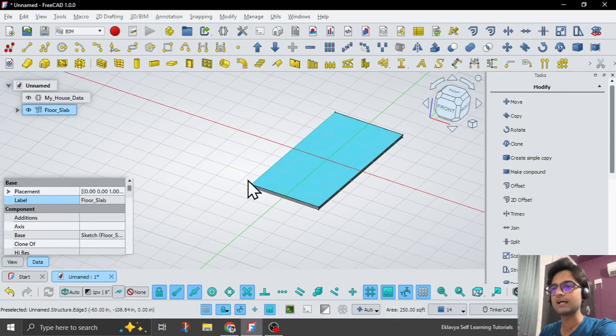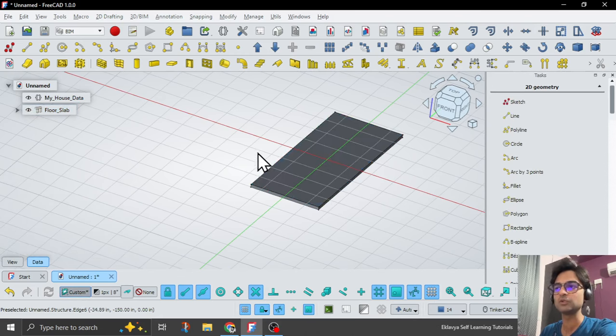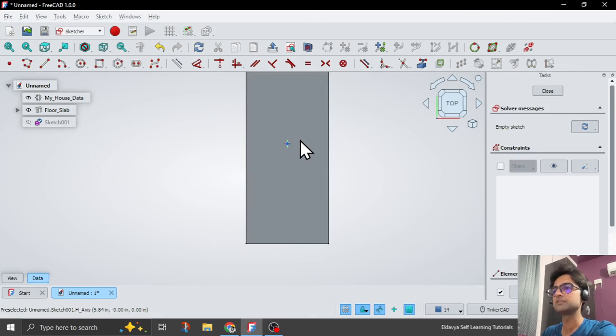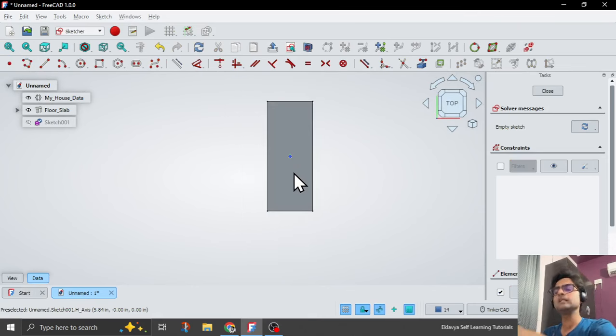We click on this slab, and here we have this setting of the current working plane. I click on this, and now the work plane is set to the top of this slab, which anyways was the origin working plane. I'll make another sketch which is on top of this slab now, and I would like to add the boundary walls, but I would also like to leave the space for the curtain walls at these two sides and at these two sides. So that kind of partition we have to take care of now here.